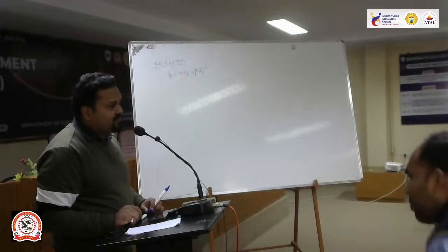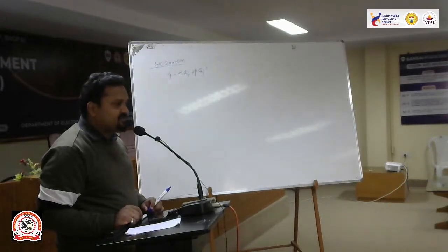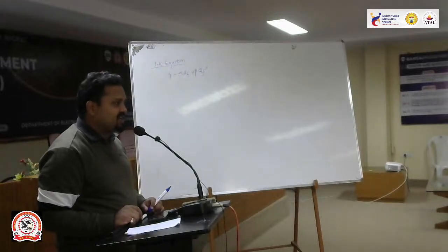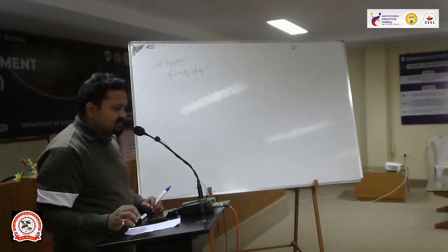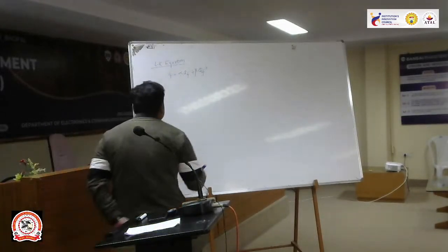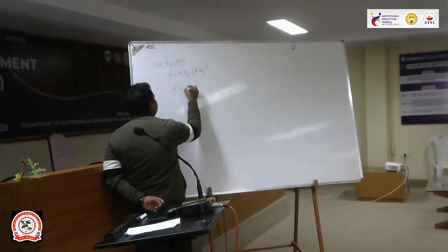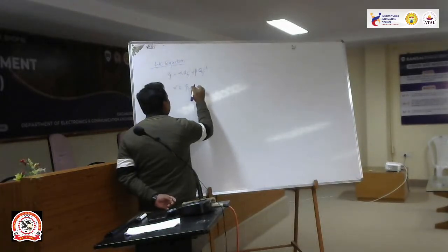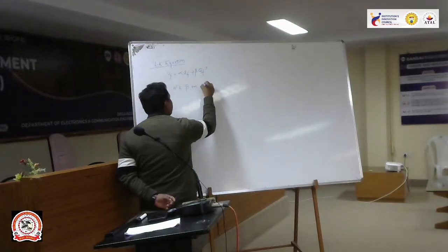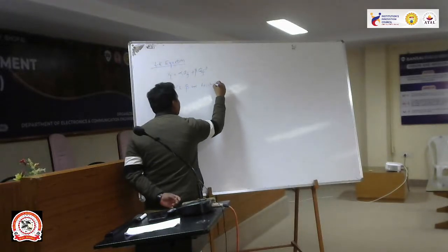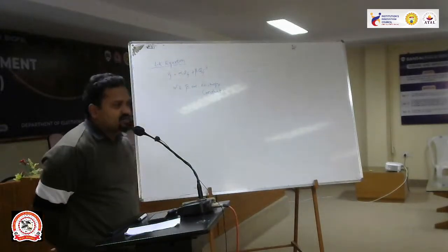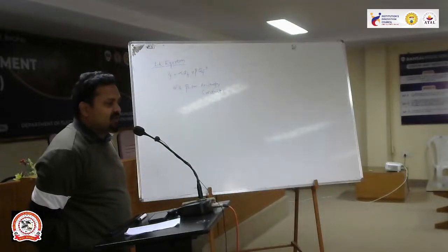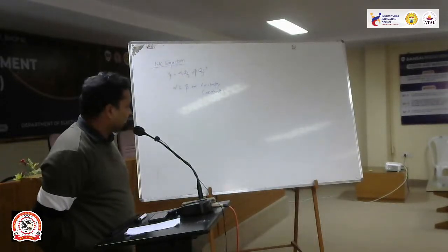So this is the equation, Vf equals alpha Qf plus beta Qf to the power of 3. Here Vf is the voltage across the ferroelectric and Qf is the charge across the ferroelectric. Alpha and beta, which I have been telling you from day 1, are the anisotropy constants. And I think in the earlier session, I already told how to get the values of alpha and beta with the help of the coercive field and the remanent polarization.